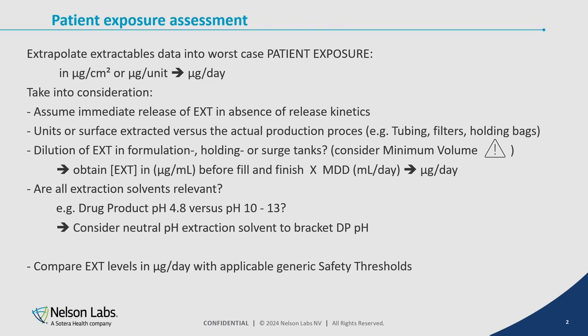That's maybe something the production engineer is not aware of. But if you say we can start filling once we reach 100 ml in the surge tank or 1 liter, your exposure will be 10 times higher if you start filling with 100 ml.